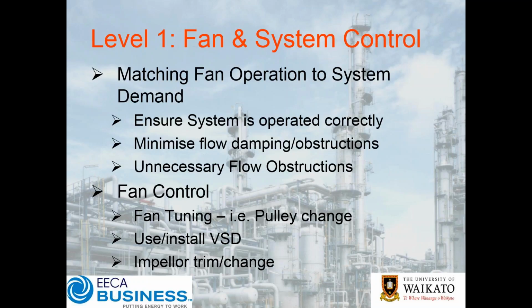Flow dampers can cause significant obstructions, and one of the interesting things there that you need to be very, very careful of is that it's very easy to have material build up downstream from these obstructions, because you get eddies and vortices generated that create dead spots in the duct where material being conveyed can drop out as the flow rates drop. With unnecessary flow obstructions, we get more back pressure, which is obviously going to limit the capacity of our system.